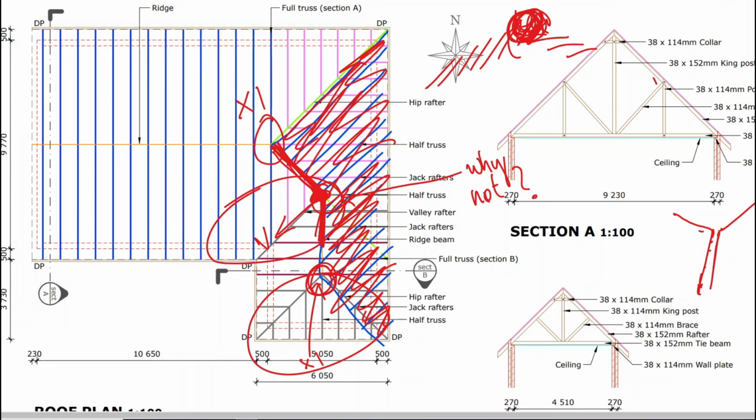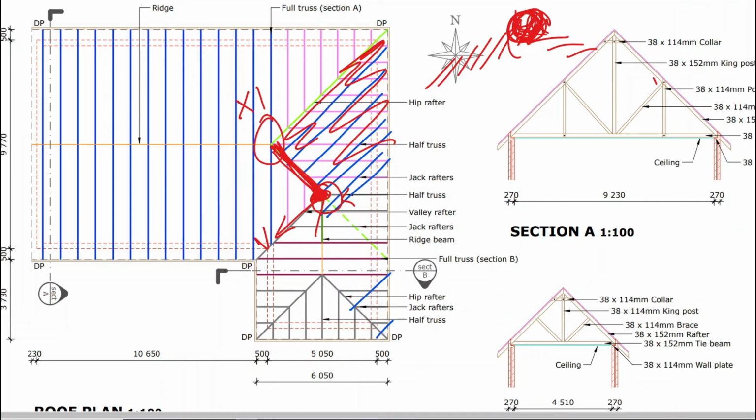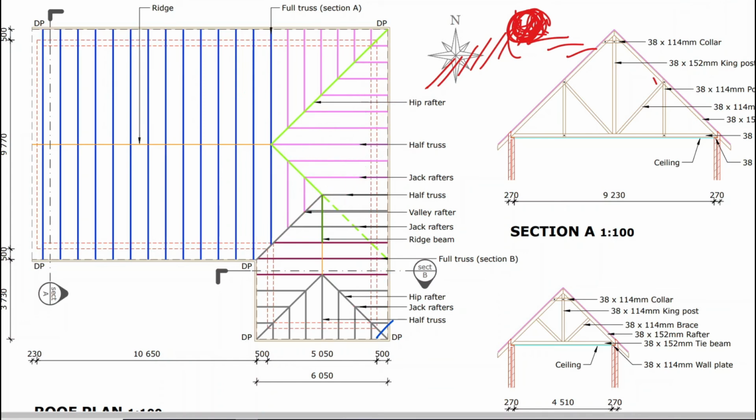It's not requiring any lapping of tiles like the ridges. The ridges require lapped tiles and very intricately sort of waterproofed. It needs that membrane, that embossed damp-proof course, and it also needs a purpose-made tile. The valley is not the same, so you need to be really careful to visualize the drawing correctly. A lot of this stuff, in my opinion, comes down to how you visualize what you're dealing with. And if you don't visualize it properly, you could make a mistake. You're going to pay for it dearly.